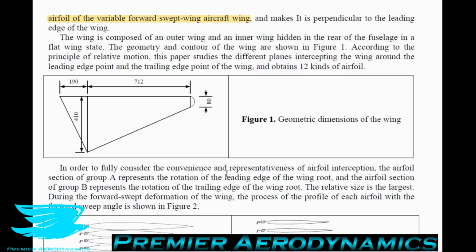So if you think about, let's say you have a regular aircraft, a regular airplane, and you have its wing. Now, to sweep this wing forward or backwards, if let's say you pivot it around the leading edge, if you pivot it forwards, now there's going to be a gap between the trailing edge root and the fuselage because now you've pulled that part a lot forward. You need extra material to make up that little bit, that gap here.